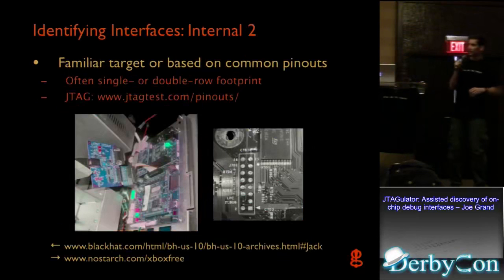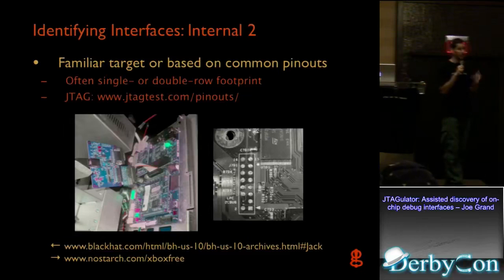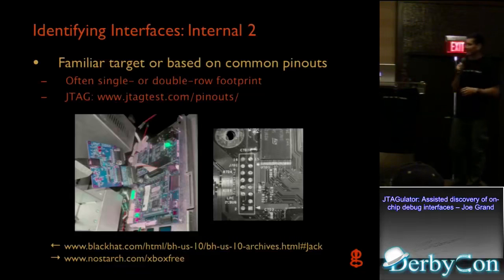Sometimes you do encounter boards that make it much easier for you, just like the cordless phone. In this case, here's a Windows CE based platform from the ATM that Barnaby Jack had hacked a few years ago, where he opened up this board, had physical access to the device, and used a common industry standard pinout for JTAG. So all he had to do was buy an off-the-shelf JTAG interface, plug it right in there, connect up to his computer, use the legitimate design tools, and start hacking the ATM. That was a really nice thing that they did for that ATM.